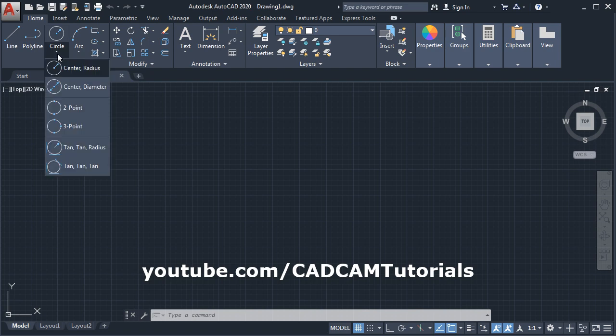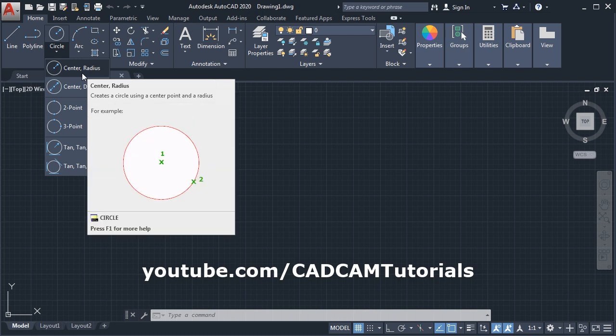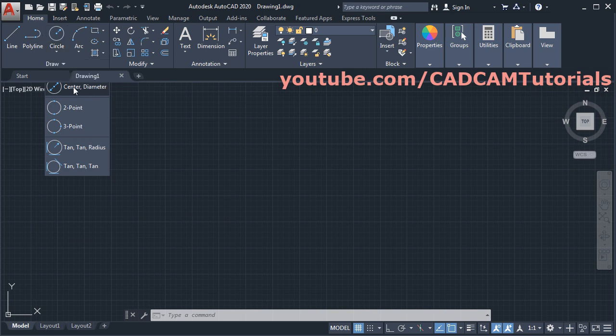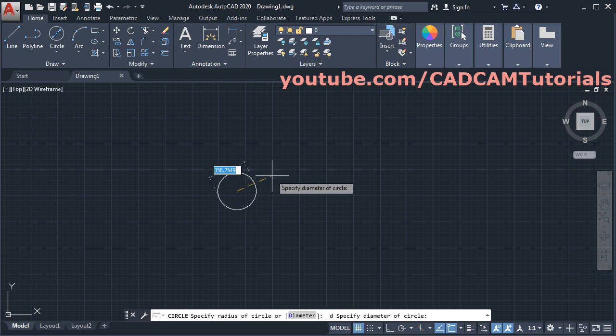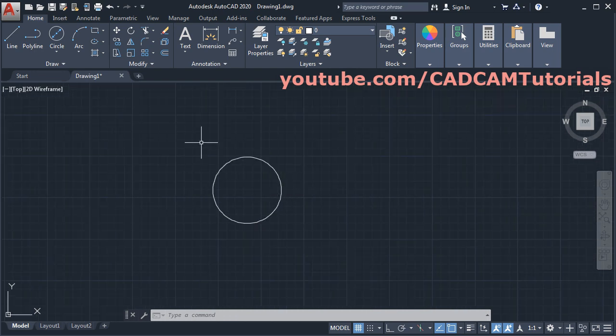Click on the arrow below the circle command. We have already seen how to create circle using center radius method. Then next is center diameter. Click on it. In this, at first you will have to give the center point for the circle. Click center point, then take your cursor away. Then you will have to specify diameter of your circle. Suppose diameter is 400, enter. So it will create circle of 400 diameter.